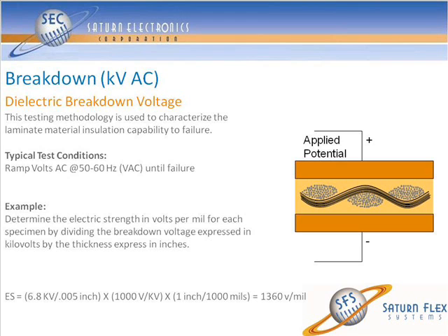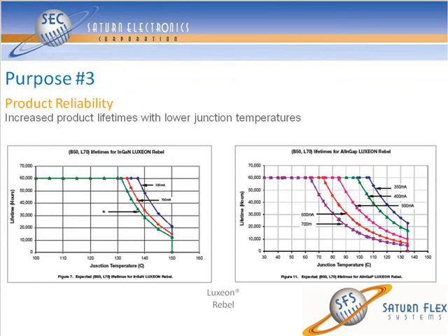As well, I hope they develop some life cycle testing. What makes a material reliable? Just because I'm putting dielectric on a metal doesn't mean one material is the same as the next. You've got adhesion issues, you've got voltage breakdown issues over time, as was previously mentioned, and it'd be great to see some standardization. But until that's done, it's always good for the OEM to come up with their own methods, and maybe sometimes they become adopted as the status quo for the industry.